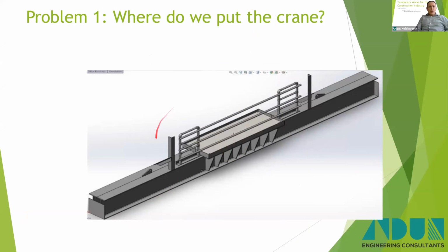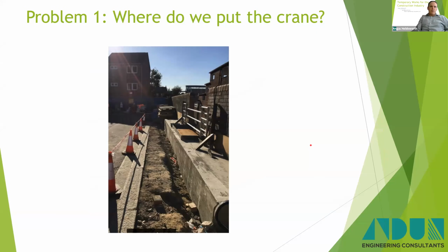It was delivered to site with this hand railing system already installed, because as it's installed, we had to take out part of the masonry wall here. So this handrail system was built in as part of the support. So you had no edge protection issues, no open edges from the very beginning. It also had bases here to allow us to prop the wall.